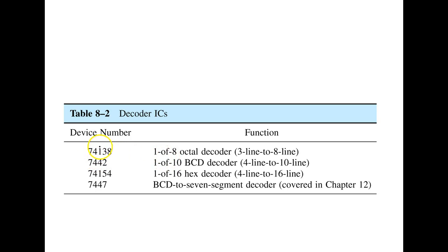If you're looking for the pin out, you're not worried about the middle letters, because the pin out of the 74138 is exactly the same as the pin out for a 74ALS138. The only time you're concerned with those center letters is if you're trying to figure out how many things this guy can drive, or speed or that other kind of stuff.